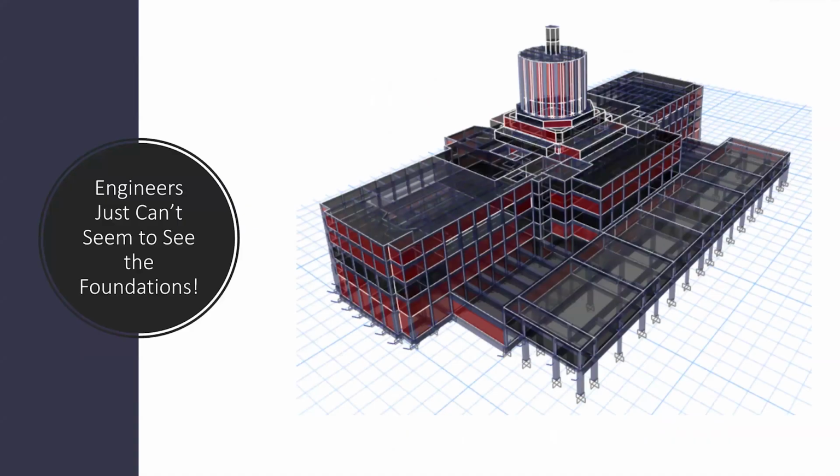Okay, now let's come to the interesting part. These are models from real buildings, by real structural engineers who are very famous and have done tons of buildings everywhere. So it's not just a class project that somebody didn't do properly. Look at the person who modeled that thing on the top, which has nothing to do with structural design. It shouldn't even be there, because it's not part of a structural analysis. And the person has modeled many, many small openings, gone into trouble. Why? Because the CAD model was like that. They imported it from the CAD model. So every detail comes in and they model everything because it's so easy.